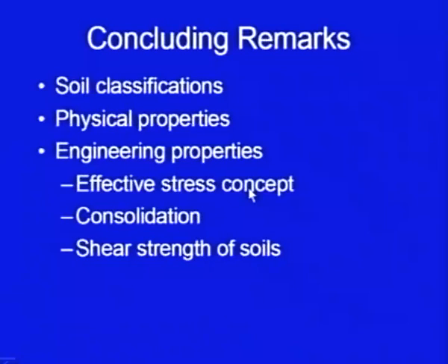Please remember, wherever you want to find out the strength, you have to use the effective shear strength parameters. You have to use effective normal stress. Then we have discussed the consolidation of the clays. It is a time dependent phenomenon, and wherever the clays are there, you should expect to get time dependent settlements. So, we have discussed this also.